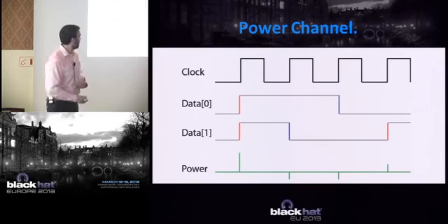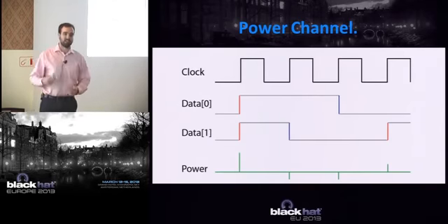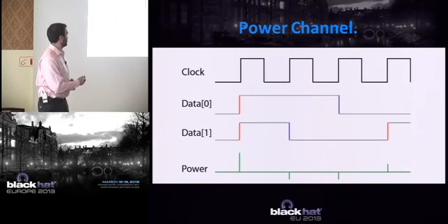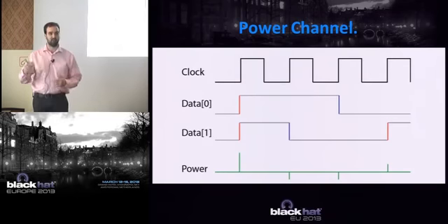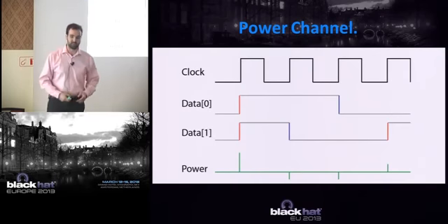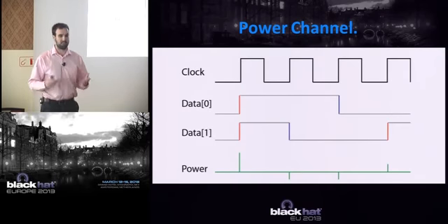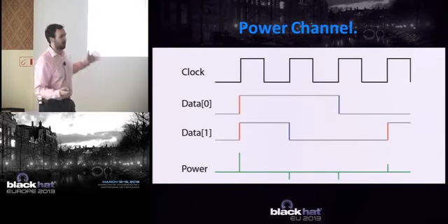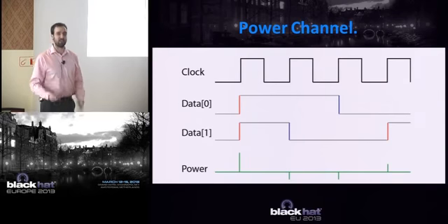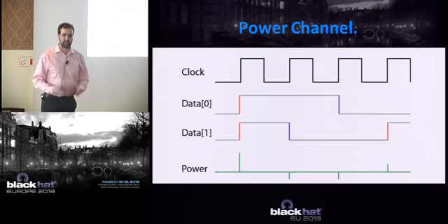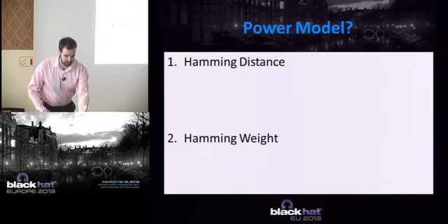It takes this power. So if we looked at the power in an ideal manner, what you would see is on each clock edge, some spikes, either in the VCC rail or the ground rail, depending what the state is. So this very basic observation is everything you need to know about power analysis. This is the root of why it works: it physically takes power to change the state of a normal data bus. And based on this, we can break everything else, which I'll explain next.